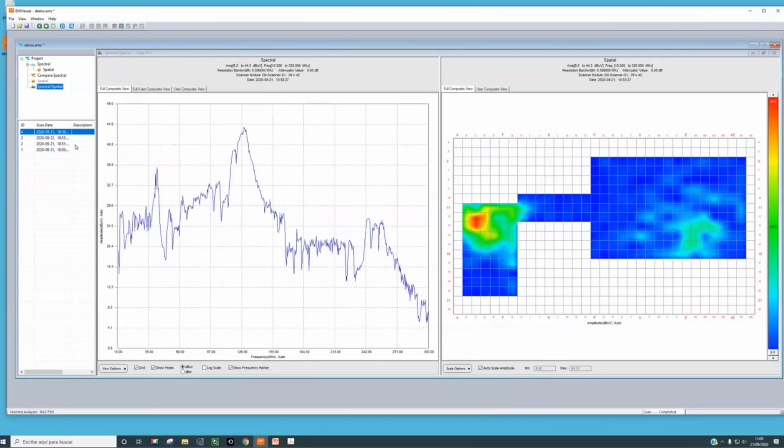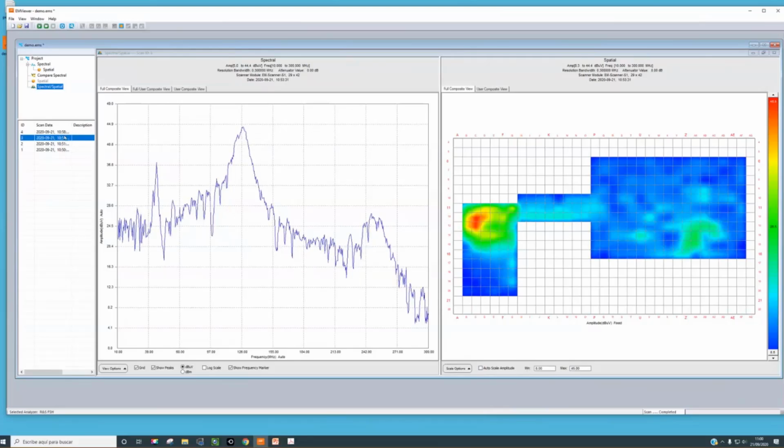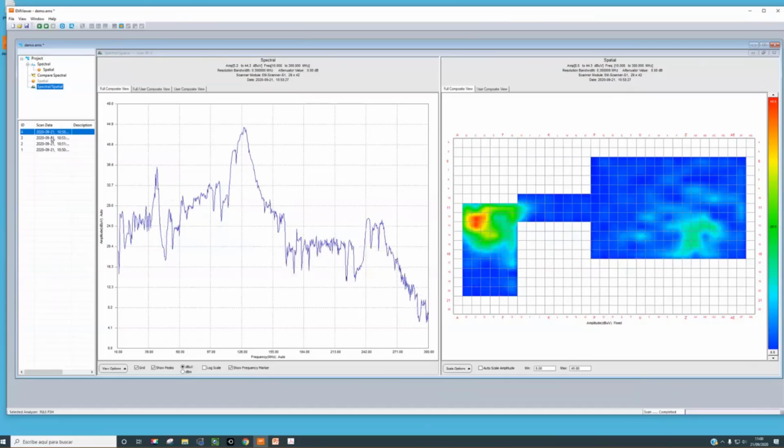So with the colors, you can see the difference. When there is no ferrite in the cable, part of the energy that is created in the DC-DC converter can go to the other area, so the full system can radiate 126 megahertz. But when you put the ferrite in the cable, you can see that the 126 megahertz signal is here. Obviously, it's created here, so the ferrite doesn't change the possibility to create it, but the energy is not able to go to the other PCB.